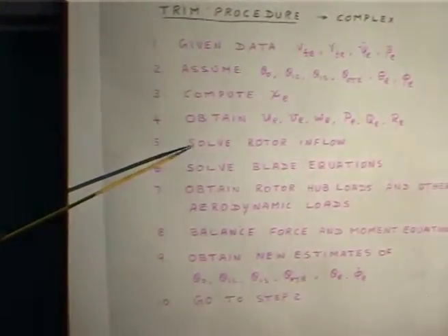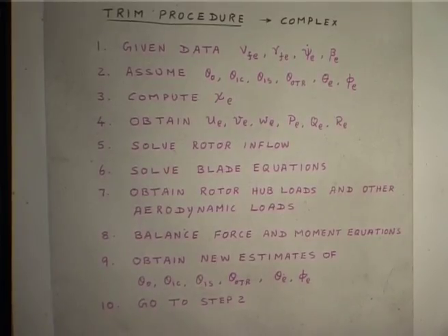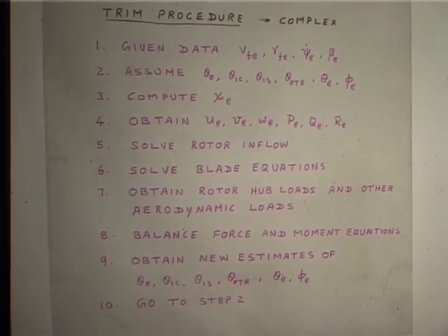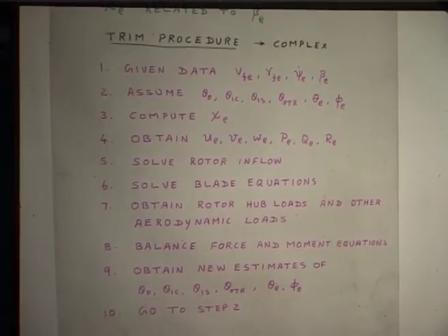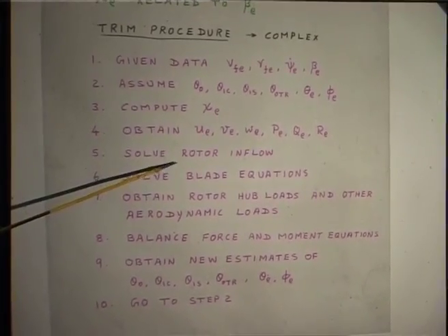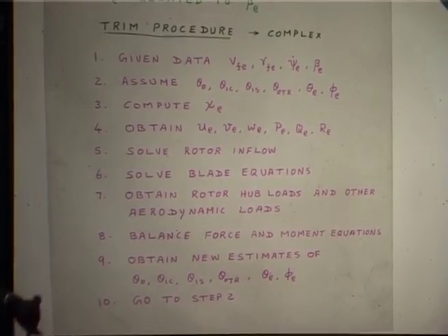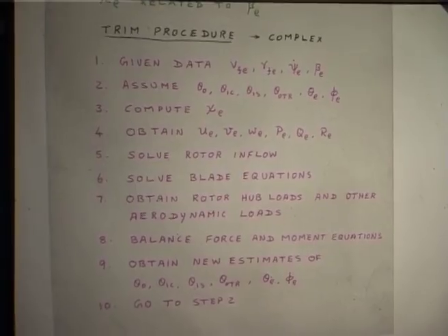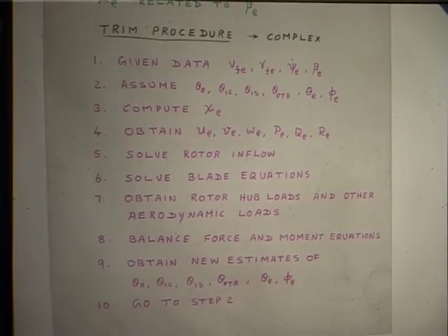Then you solve rotor inflow. You may assume uniform inflow or any other inflow, first assume that. Go and solve rotor inflow. Once you get the rotor inflow, then you solve the blade equations. Even if you have only flap equation, just solve that, but you should write the flap equation based on a